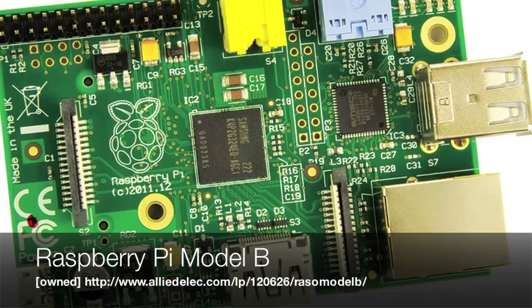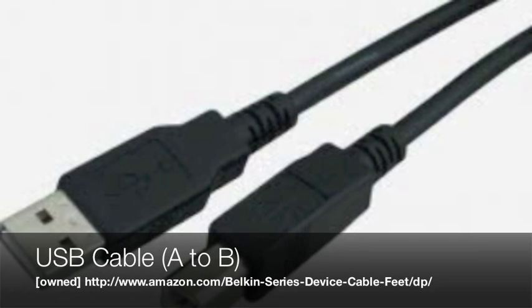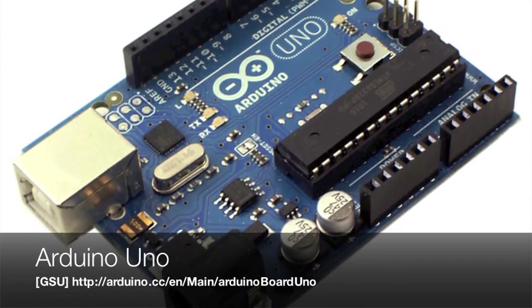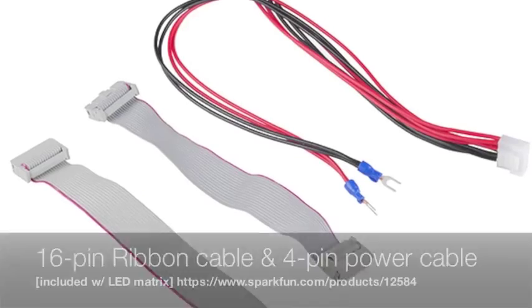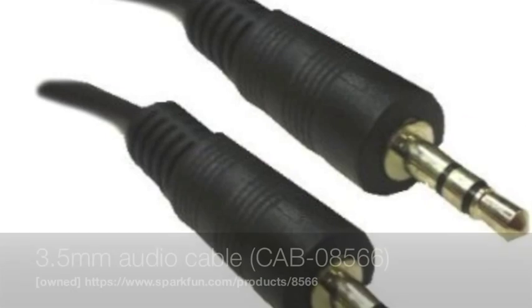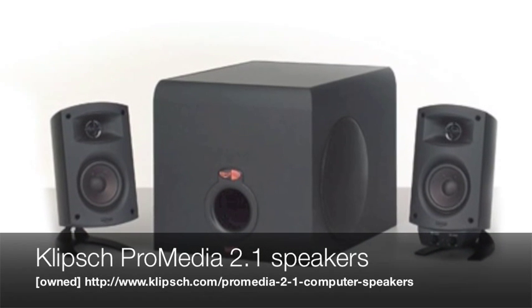So to do this, let's look at some of the hardware we're going to be using. We're going to have a Raspberry Pi Model B, and we're going to need an A to B USB cable because we're connecting the Raspberry Pi to the Arduino. And the Arduino is going to be used to power the LED matrix, and that's going to be connected via a 16-pin ribbon cable and 4-pin power cable, which are included with the matrix. We're also going to need just a simple auxiliary cable and some sort of speakers. Those are just the ones I own.